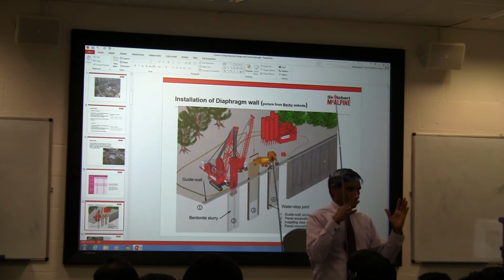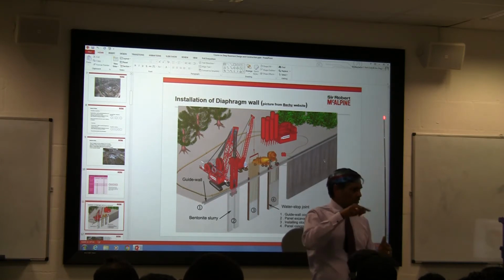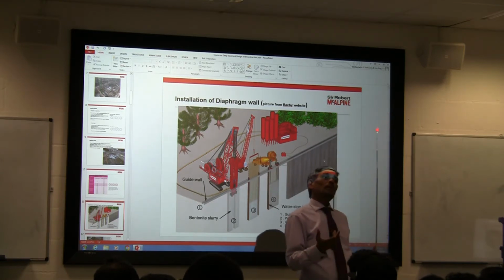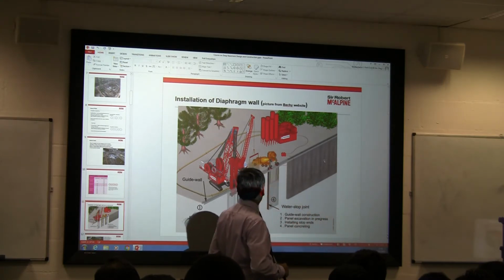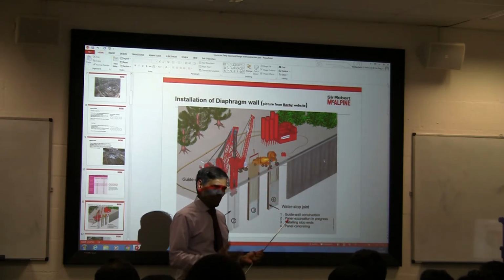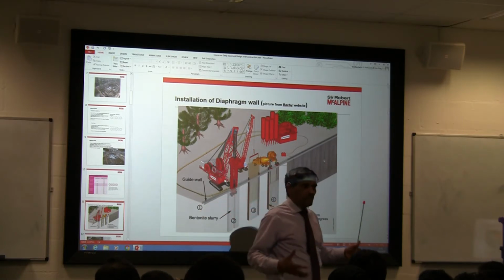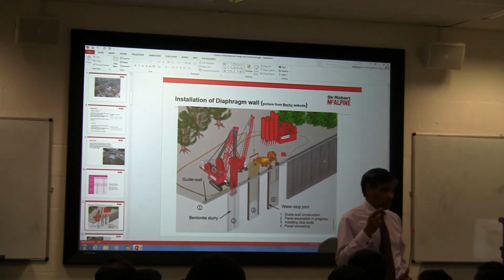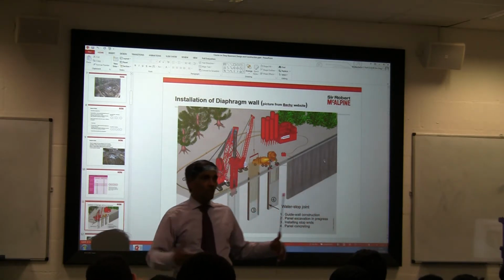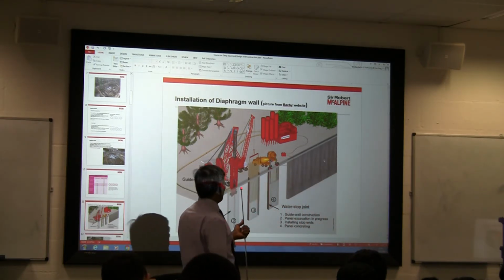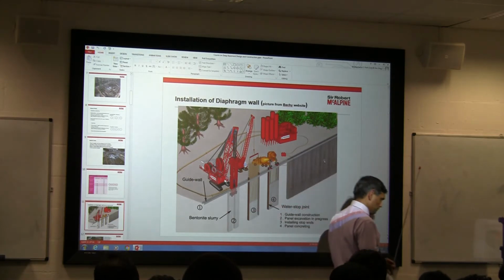It's going to move. Because you restrain, your horizontal strain is 0 at the point of hole. So it's going to relax. When you're going to relax on the ground, when you temporary condition, it's going to move the structure there. So you got to think about these things. What is the movement during installation of diaphragm? This is very important. As the bigger trench you open, more movements will come. Yeah? So this is a diaphragm wall construction.